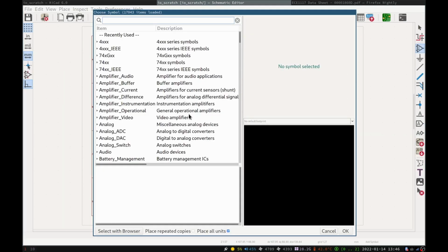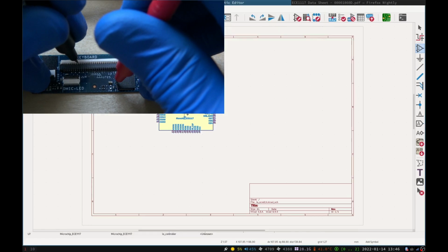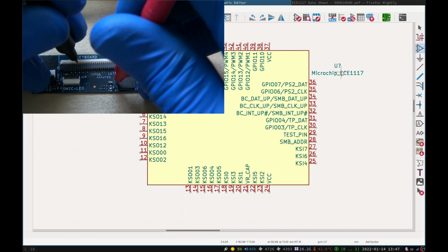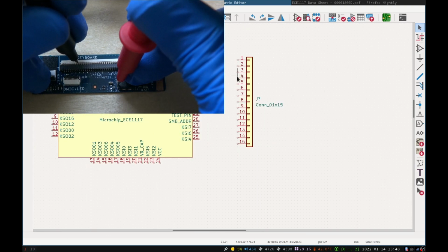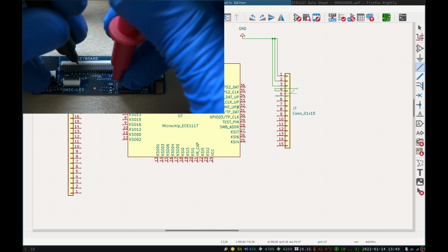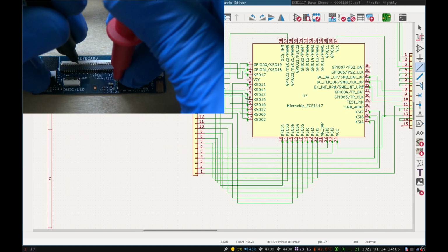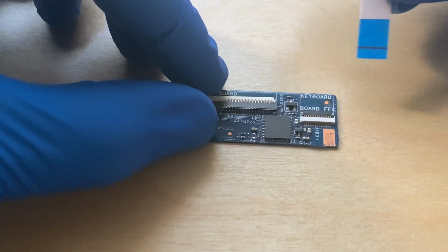Now that I have this chip in hand, I tried to reverse engineer the circuit with some basic analysis and just a $20 multimeter. Using the datasheet for the appropriate pinout diagram, I quickly sketched out the circuit. I attached a breakout board for the 0.5mm pitch FPC and verified everything was where I thought it should be.